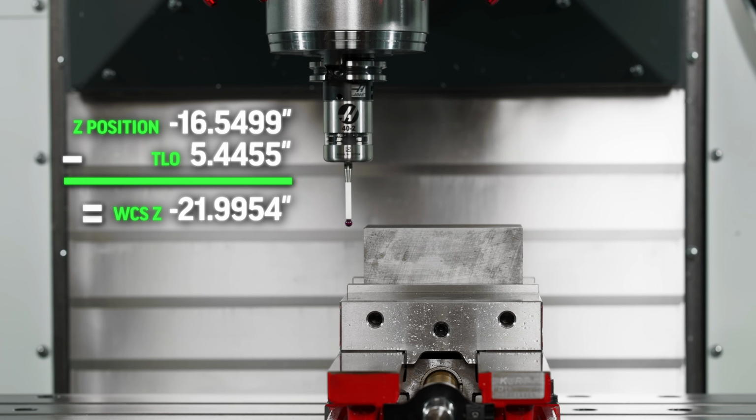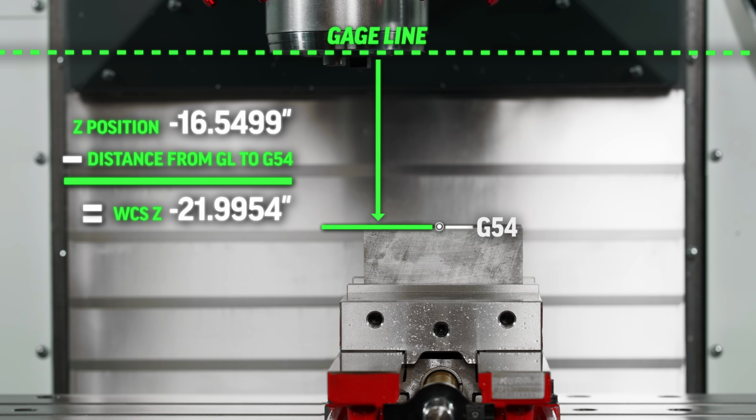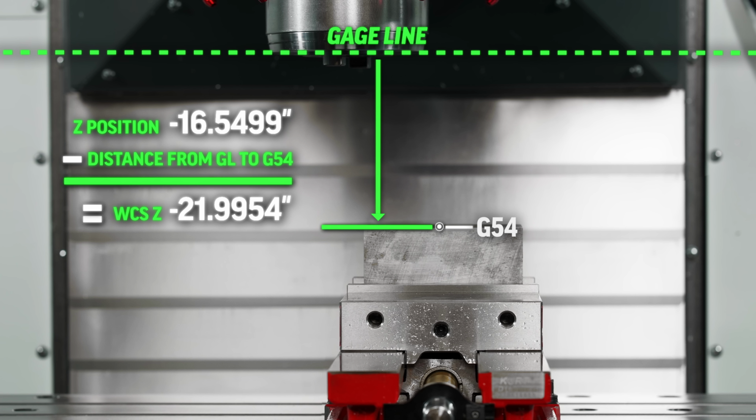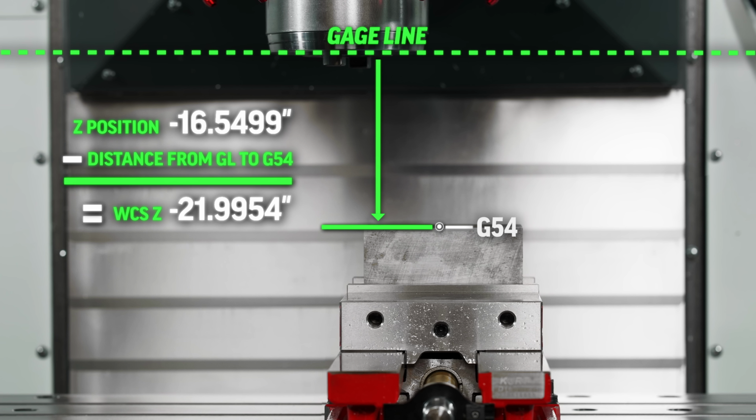Machine Z position minus our probe length offset. Now with that probe length removed from the equation, it means that our work Z0 is really just the machine position where our spindle gauge line meets our part.